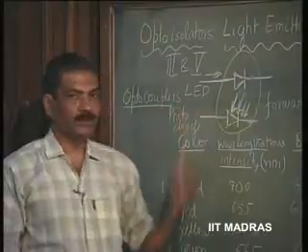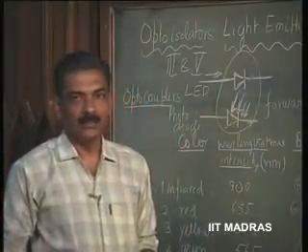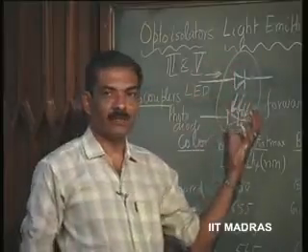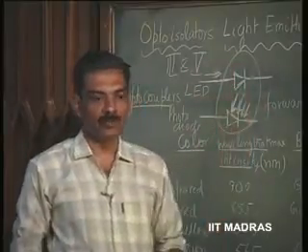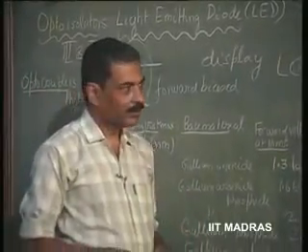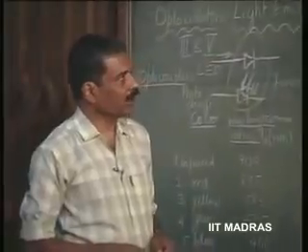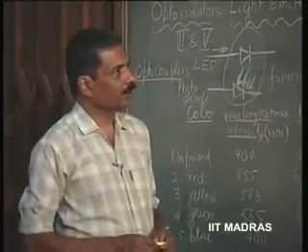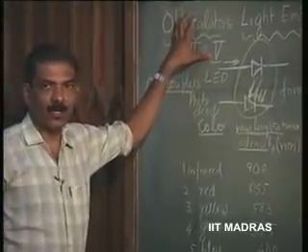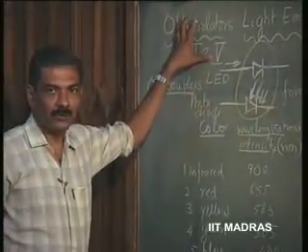You would like to use some electronic element like this which is quite convenient. Very intelligent designs are available where this can be used for precision measurement of current in high voltage circuits, etc. So, this is another application of this combination of photodiode with light emitting diode, which is called optocoupler or opto isolator.